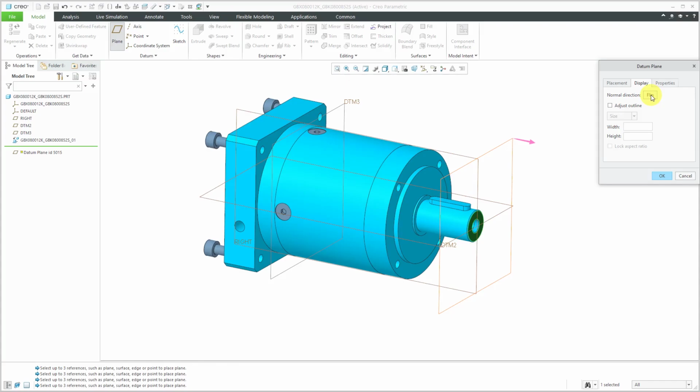And that's something that was a lot more important in earlier versions of Pro Engineer, not as important these days. One thing that you might notice, it's hard to discern these days, but if you rotate a model, you'll actually notice that one side of the datum plane by default is brown and the other is gray, but the colors are so close to each other, it's hard to tell the difference. In earlier versions, they were yellow and red to make a bigger distinction between the positive and negative sides of the datum planes. And again, it was a lot more important for sketching and patterning back in the day, but not as important anymore. So if you do want to change the normal direction, you can.